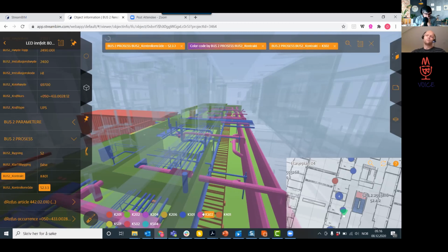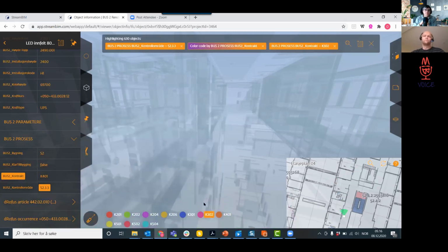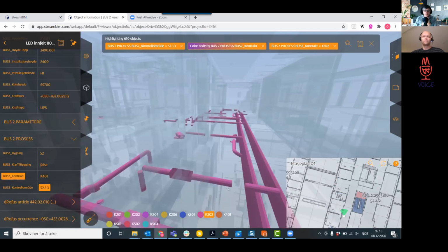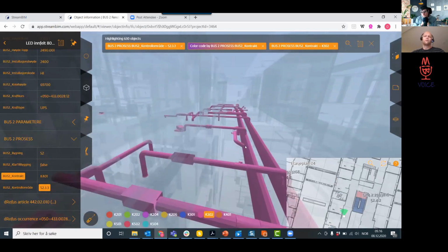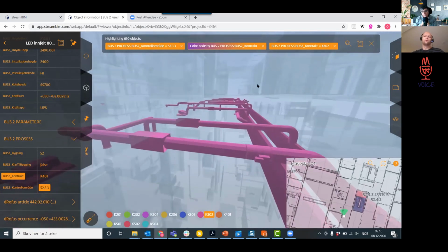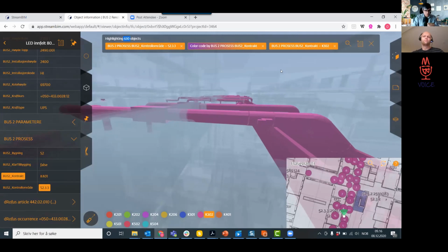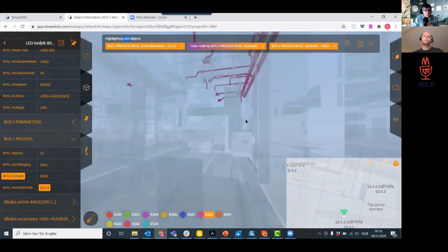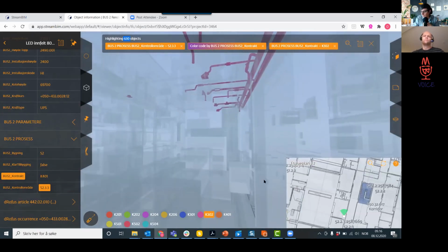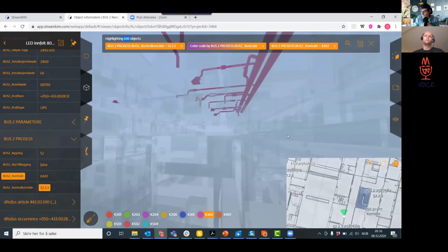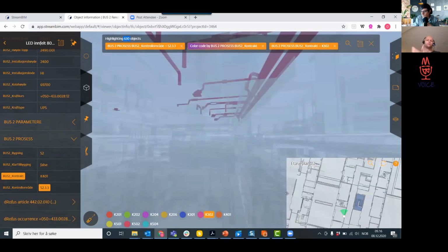If you look at only the mechanical, you will see that it's basically only ventilation. You also count these objects. So the ventilation contract, mechanical, is 630 objects in this production zone. Interesting. So it's quite easy to navigate through, filter, search, group, etc.